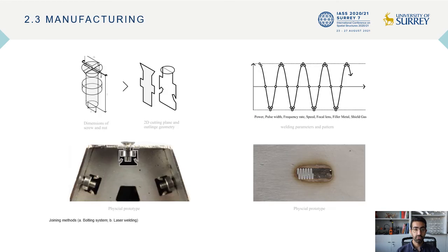Manufacturing development consists of strategies to assembly process and plate joining. Two strategies have been explored for plate joining. The bolting method allows for orthogonal reversible join between the stiffeners and the bent plates. The second strategy is laser fusion welding, which creates a strong and durable bond through a localized fusion of the two materials.